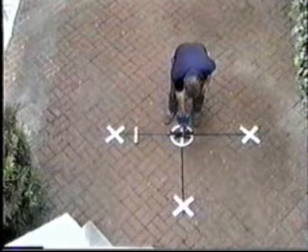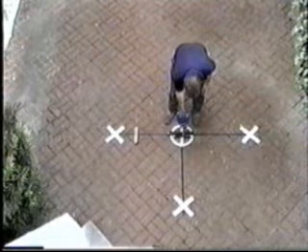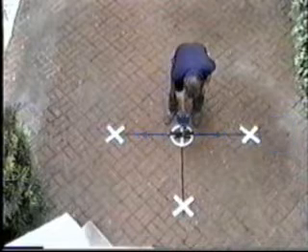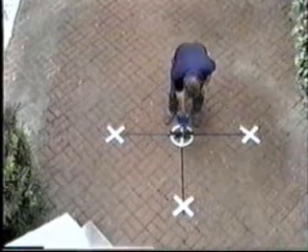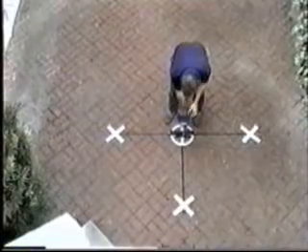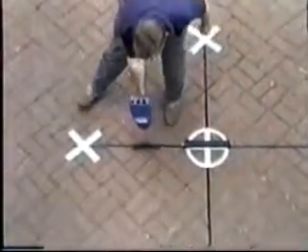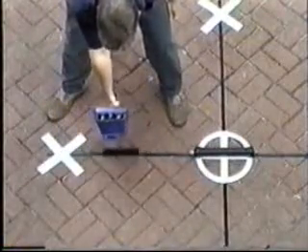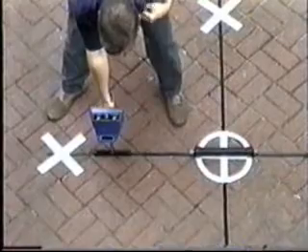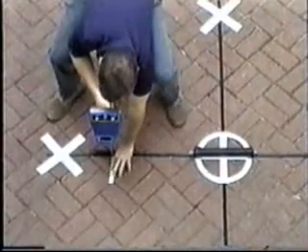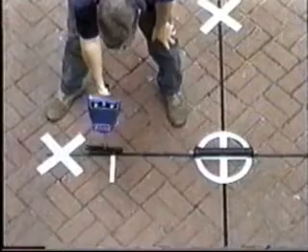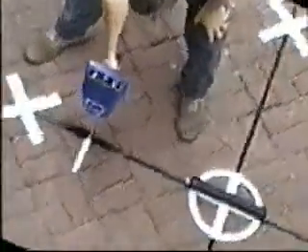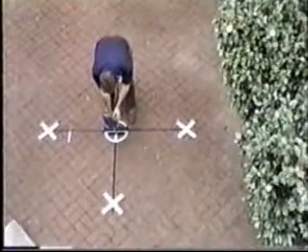To find the first depth null, hold the horizontal detection antenna directly above the location mark and aligned with line B. With the sensitivity of the receiver on low, turn the gain of the receiver all the way up. Now, slide the receiver to one side of the location mark and along line B. When a dead spot occurs, pinpoint and mark this location. This is the first depth null. To locate the second depth null, repeat this procedure on the opposite side of the location mark.